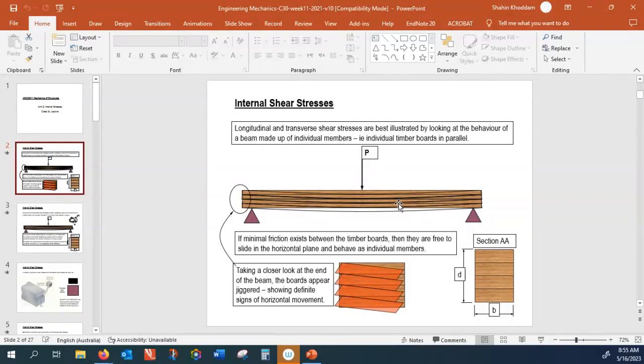Okay, so this is not the reality. The reality is, if that's a wooden beam, all layers are glued together by wood. So it is really the wood which is enduring the shearing stress. If that was made of any material, when you try to bend, those imaginary, virtual layers would tend to slide, and what stops them from sliding is the material. So you can think of these stresses developing between the layers. And when I say layers, it means in the transverse direction, you see a difference.